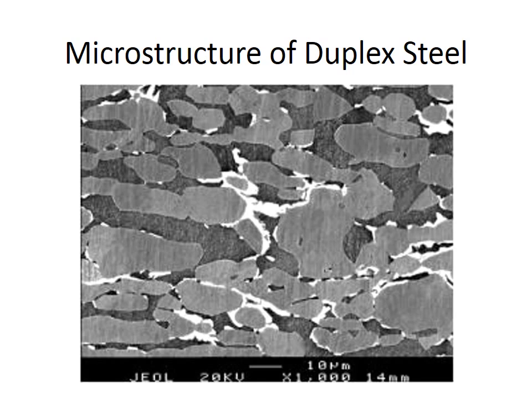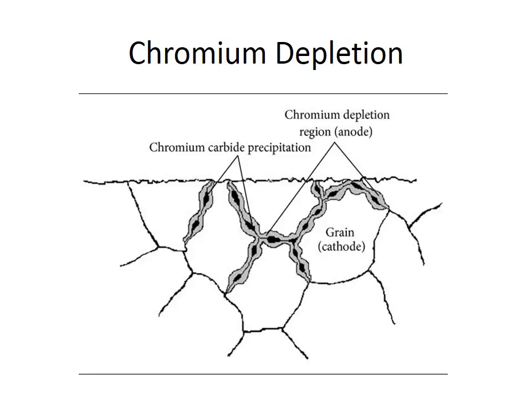tanks. During the formation of stainless steel, sulfide molecules attract chromium atoms, which creates a dearth in chromium concentration surrounding the sulfide. This creates concentration disparities that are the sites for the steel corrosion cracking. Ridding the steel of sulfide would mitigate corrosion, but would also make it harder to mold the steel into the desired shape and structure. This is where the use of duplex steel as a replacement comes in.